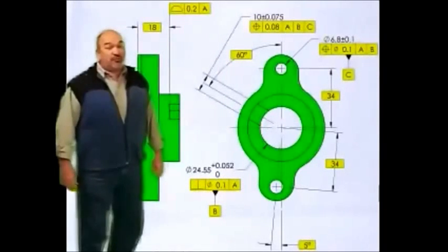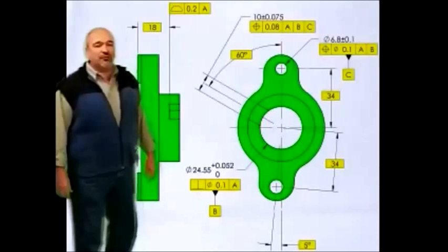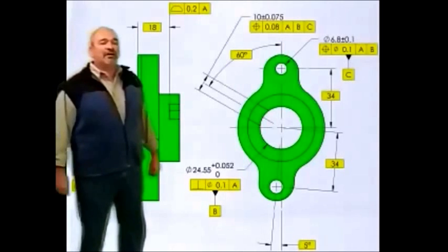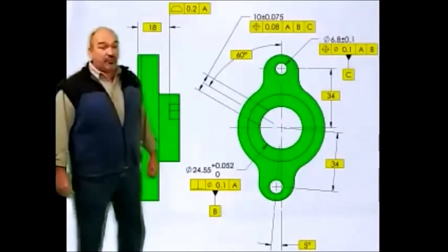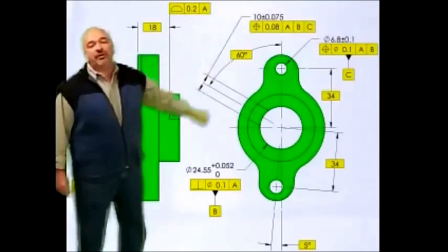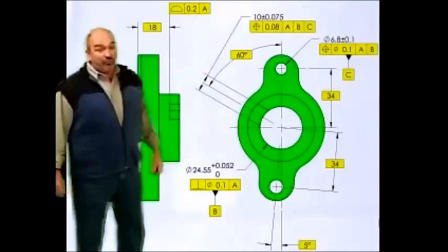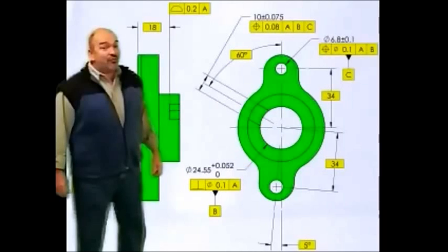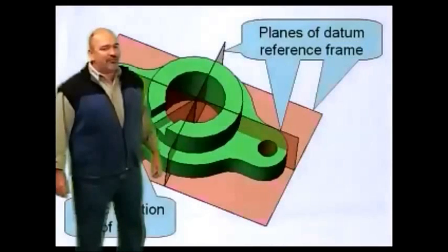This is a problem that just won't go away. Here is another case where angularity cannot fully define the feature. The original drawing had angularity rather than the position tolerance applied to the 10 mm wide slot. The drawing shows that the center of the slot should be in line with the datum axis.